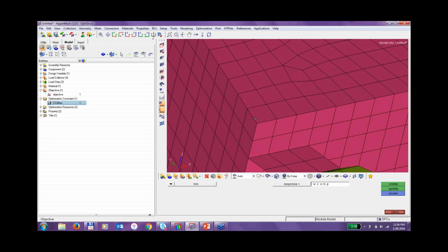And it is taking the Young's modulus of the material for each one of these elements, and it is multiplying it by a value between 0 and 1. And we know that the Young's modulus is essentially the strength of the element, or the strength of the material. So if I multiply that Young's modulus by 1, I'm saying that element is absolutely necessary, and it has to give everything that it can give.